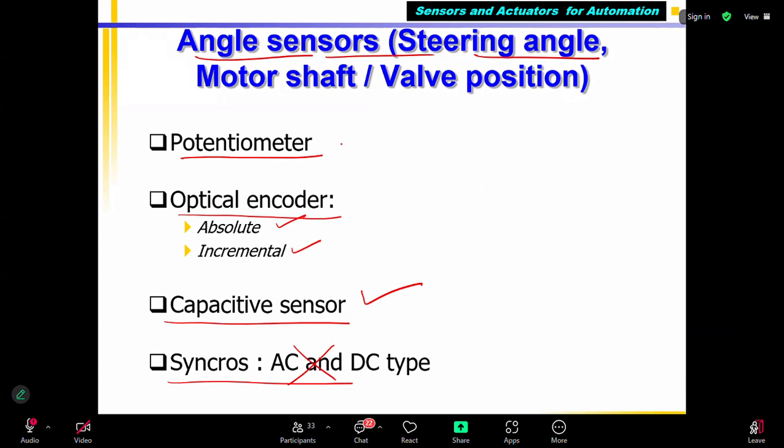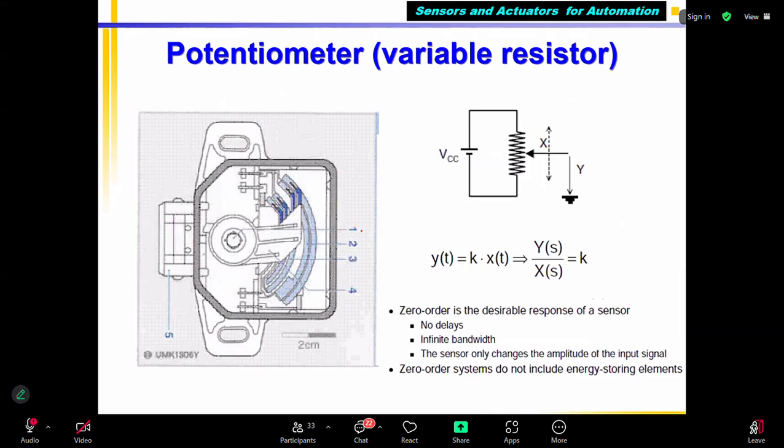These two sensors: the TPS sensor, the throttle position sensor, measures the throttle angle when you press the throttle shaft. Okay, so that is one. The other one, we'll see one by one quickly. The TPS sensor is nothing but a potentiometer, a variable sensor, correct?